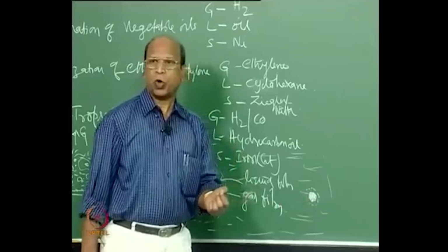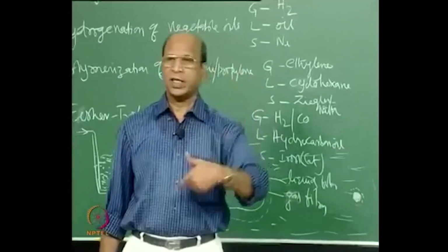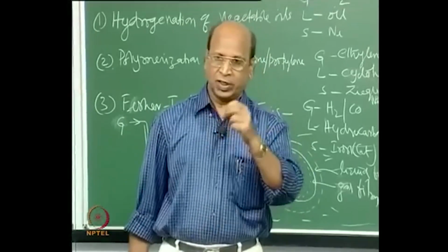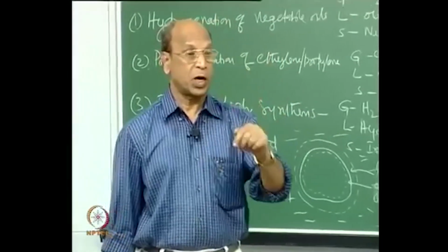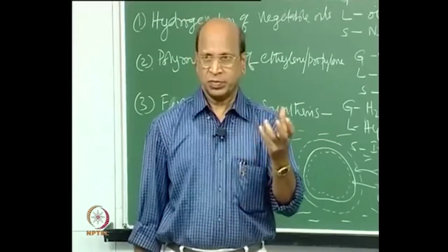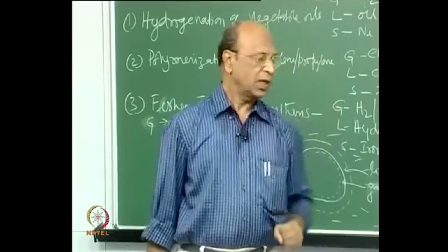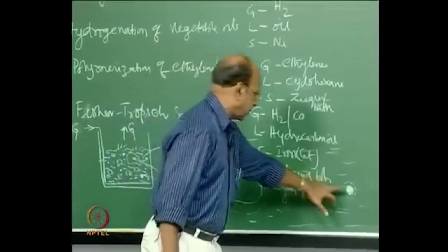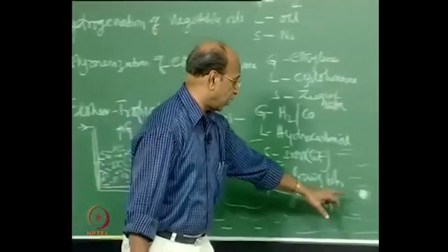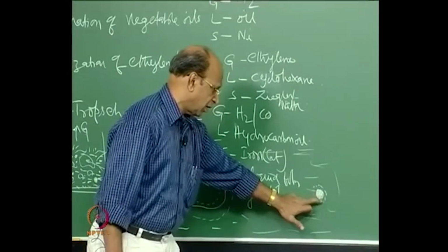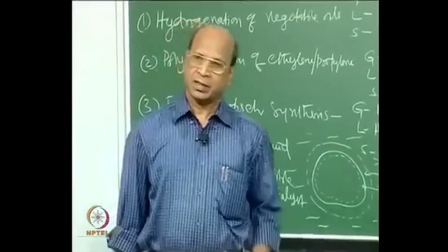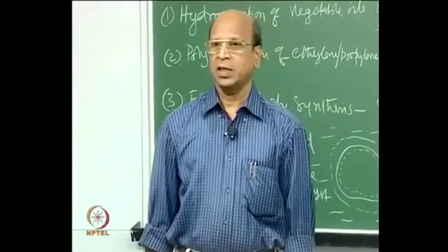If the particle is not porous, then reaction occurs only on the surface. If it is porous, then again the reactant has to diffuse inside, but now it is in the form of not gas but liquid, correct? No, the gas has to dissolve in the liquid, and that dissolved reactant will go to the internal pores and then get reacted. We are experts now at taking care of this: even if I have a porous particle, if I know the effectiveness factor of the particle, then I will know the rate of reaction in the particle.